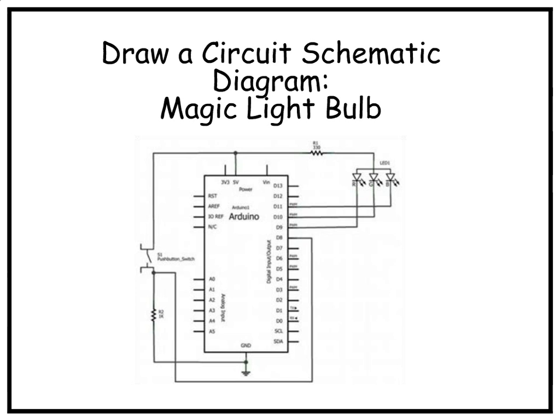Now, what's really cool about this diagram is it's bringing that block diagram to life, meaning on the left side, and hopefully you can see my little arrow, my cursor here. On the left side, we have our switch, okay? So that was on the left side. So when I do my schematic diagram, I always start with the input being on the left. Again, whatever device that is, it could be a switch or a sensor or some other electronic device, is going to give me a signal that I want the Arduino to read. It's on the left, so that's why I got my switch on the left.